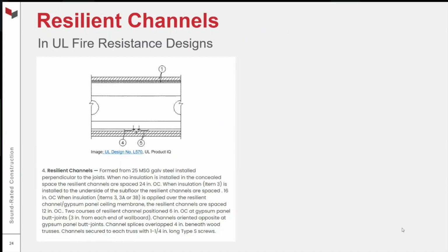So over the years, since the advent of that original USG RC1 in the 60s, you saw a lot of UL or pre-UL fire-resistive horizontal assemblies incorporating resilient channels between the joists and the gypsum ceiling membrane. That is because those resilient channels help maintain the integrity of that fire-resistive gypsum membrane during a fire test or a fire event.